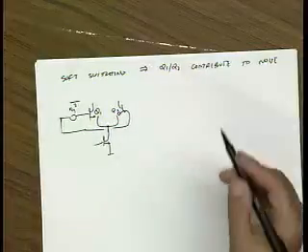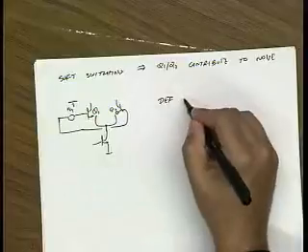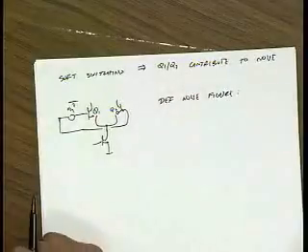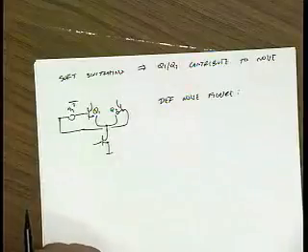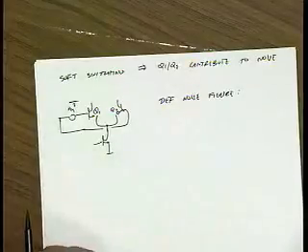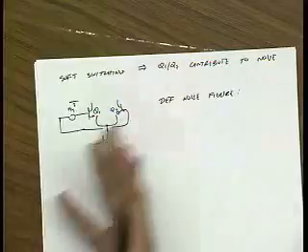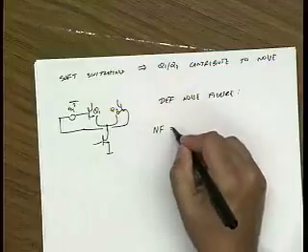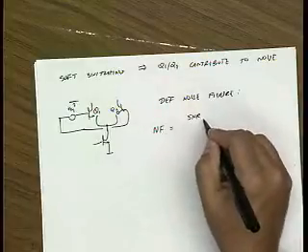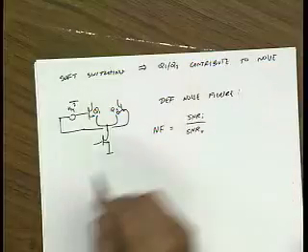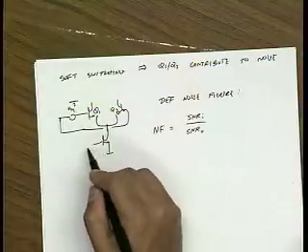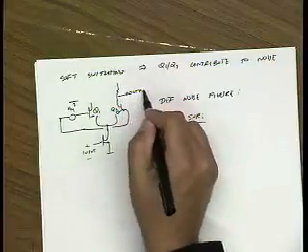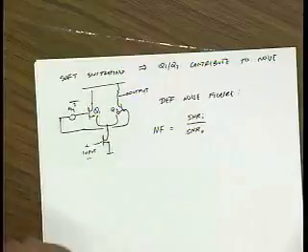Well, the noise figure, the way we define it, the definition of the noise figure is actually a little bit complicated. And there's two definitions for mixers. One is the IEEE definition, and one is kind of a microwave definition. And it's because of the fact that there's the image noise. So one way to define the noise figure, you might argue, is the same way. It's the SNR at the input divided by the SNR at the output, right? Where this is the input port, and this is the output port. Okay?